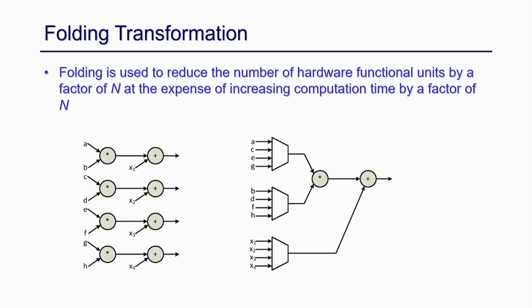Okay. Let us take this example. Suppose I am doing multiply and add, multiply and add, in parallel. So, there are 4 such components in your design. If you just think about the hardware, I have 4 multipliers and I have 4 adders, and these are all running in parallel. So, what we can do is identify this MAC pattern, multiply and accumulate, and use only one of the patterns in your design, and now the inputs should be time multiplexed.